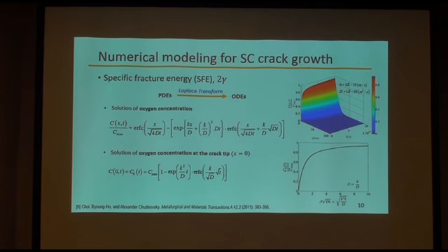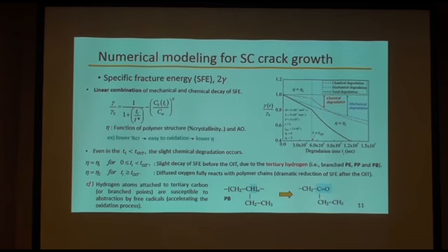By using the Laplace transform, we can obtain the analytical solution of the oxygen concentration along the process zone, like this. And by taking x equals 0, we can obtain the solution of oxygen concentration at the crack tip. And by using the superposition method, the mechanical and chemical decay of surface fracture energy can be explained like this. And an eta function is introduced to consider the oxidation rate depending on the polymer structure or antioxidant in the polymer.